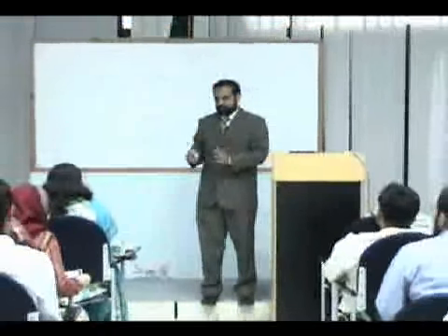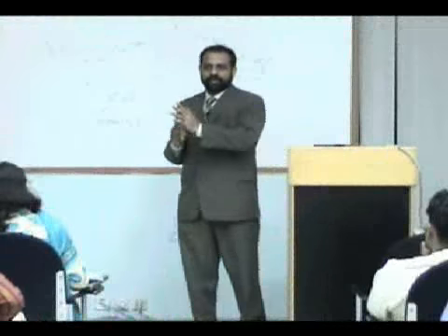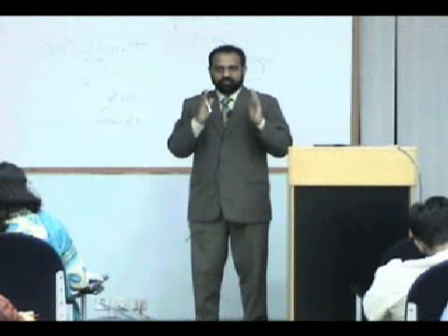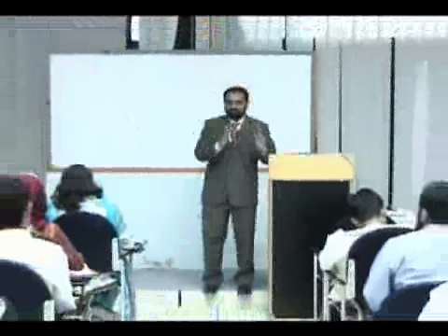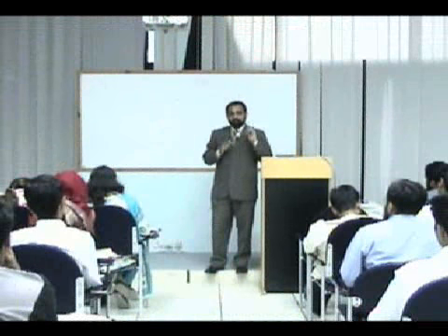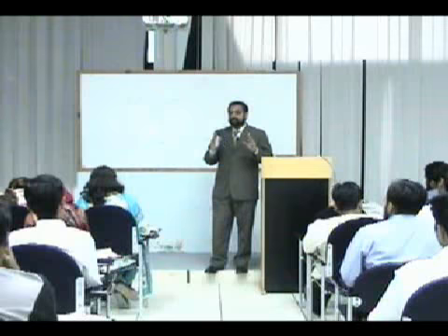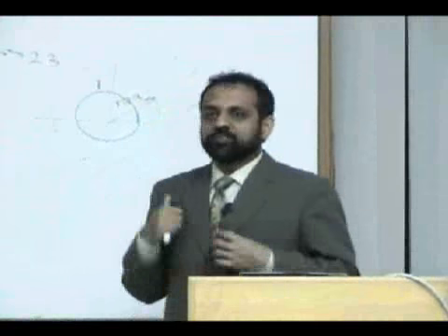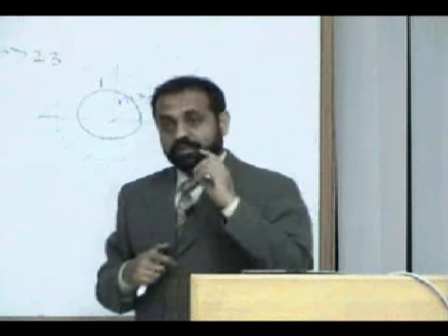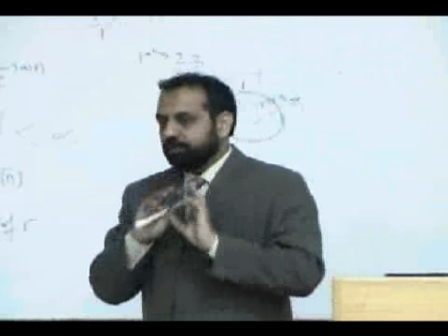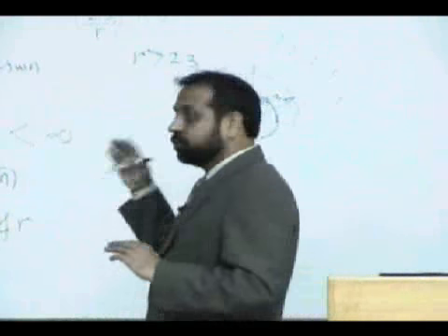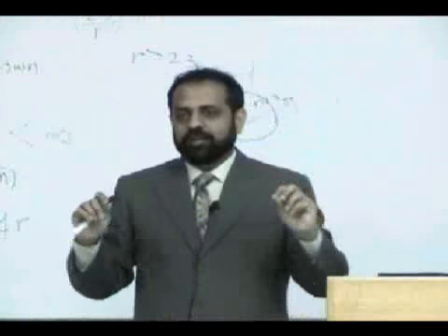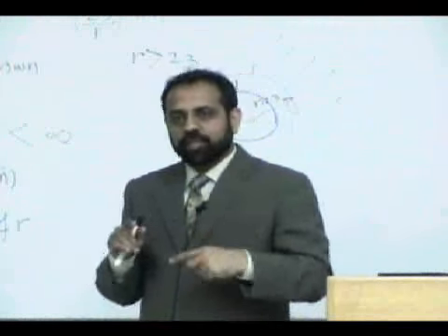But remember, in the second part of the course we will be designing on the fly. You design for a few milliseconds, the system is this, now the system is this, now it is this, and there you need to make sure whatever you design is stable, dynamically, especially in the equalization problem. All the time you are designing systems on the fly, and you have to check whether whatever you have designed is stable or not. Z transform is used to check the stability of a system. And you don't compute the Z transform the way you compute the Fourier transform, plot it and see the frequency contents, because the Z transform is also the Fourier transform for R equal to 1.